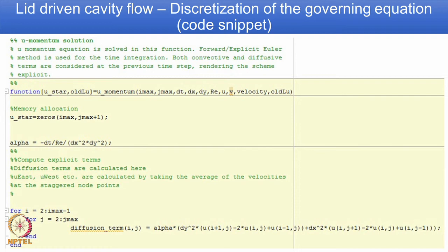So, the extra delta x squared needs to be accounted for properly, hence we have delta x squared multiplying the finite difference of ∂²u/∂y², as shown here. So, u(i, j+1) minus 2 times u(i, j) plus u(i, j-1). So, this is actually central differencing, one is the point of interest, one on the right side, one on the left side.